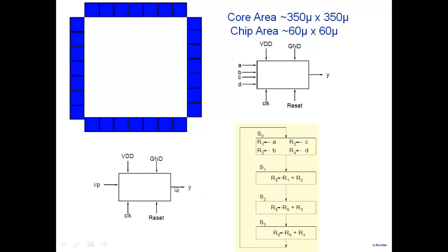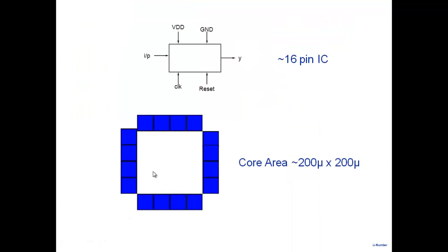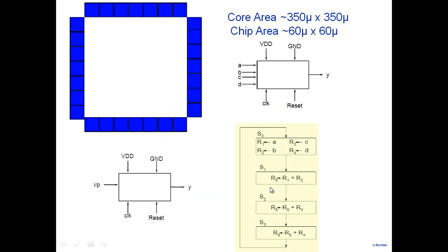But still, the point that I'm trying to bring out through this example is that at the RTL stage, when you're conceptualizing your system, you say, let me read all of them, A, B, C, D here. There's a price that you have to pay for this. The price is that if you're reading all of them, then you need simultaneous parallel data, a large number of pins, and it has implications in terms of a large area. And so one can read it serially. If one reads it serially, you see that one is minimizing the area a lot. But there's a price that you may have to pay. You may end up using more states because you're not doing everything in parallel, so more states are required.